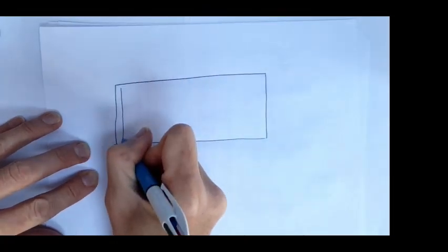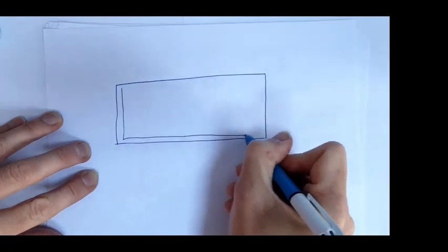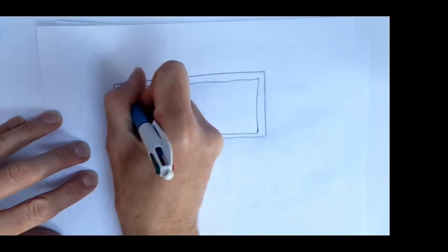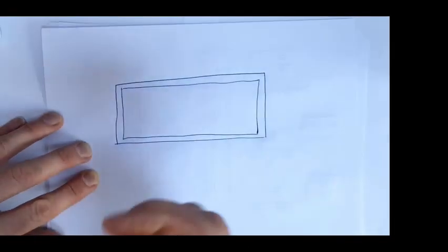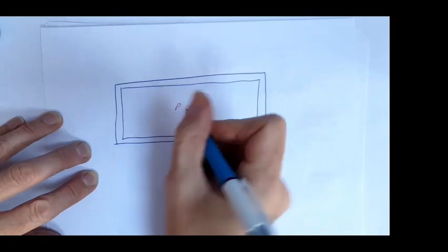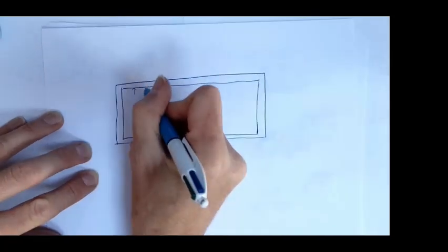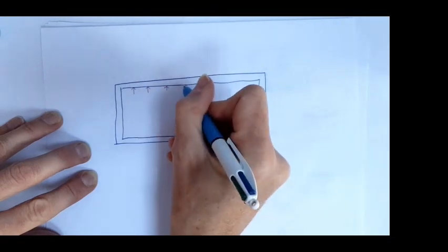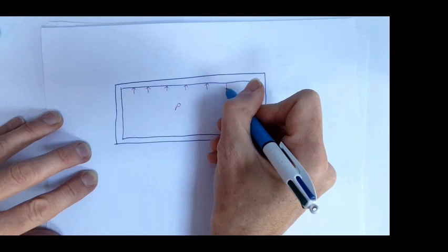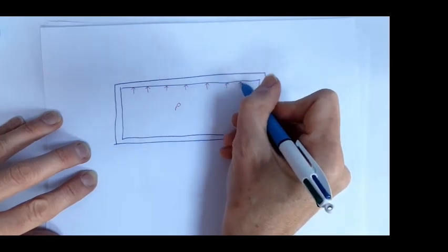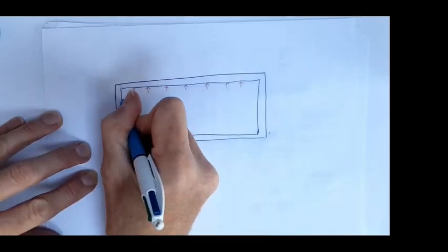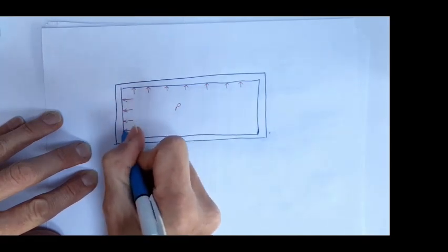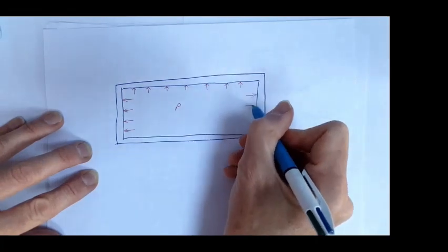It has a thickness, T. We've got a pressure on the inside of that cylinder. And we've already considered the fact that this pressure is acting on these outside faces, which is resulting in that hoop stress. We're now also going to consider the fact that this pressure is acting on these end plates, which results in our longitudinal stress.